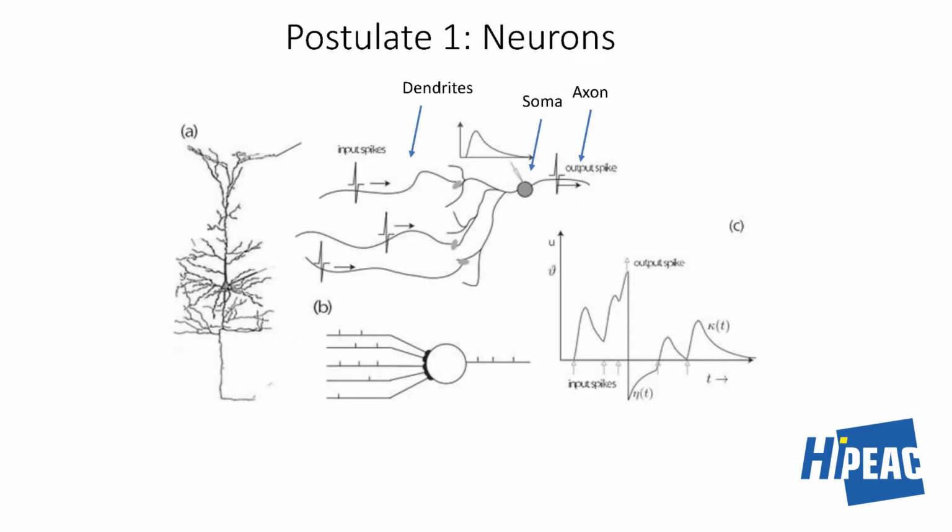Then in neuromorphic computing, there's another word that people use, dendrites or dendritic compartments. For instance, on Loihi, people talk about multi-compartmental neurons and dendritic compartments. And actually in low-level hardware, they don't talk about neurons, they talk about dendrites. The dendrites are the input ports of a neuron, if you want. They are marked here. These are the locations where other neurons connect to this neuron. The neuron has some branches, and other neurons connect to these different branches. Each branch can get connections from several neurons and can do some little nonlinearity itself.